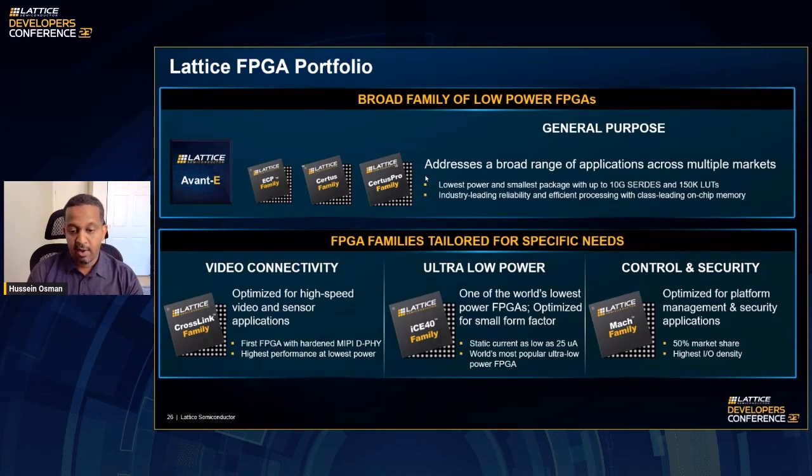On the I/O expansion and glue logic side, the iCE40 UltraPlus on the bottom middle is a perfect device for that. Those devices typically have microamps of static power current consumption, and they're as small as 1.4 by 1.4, so they can fit into very tight spaces with good quality I/Os to bring in data and send data out.